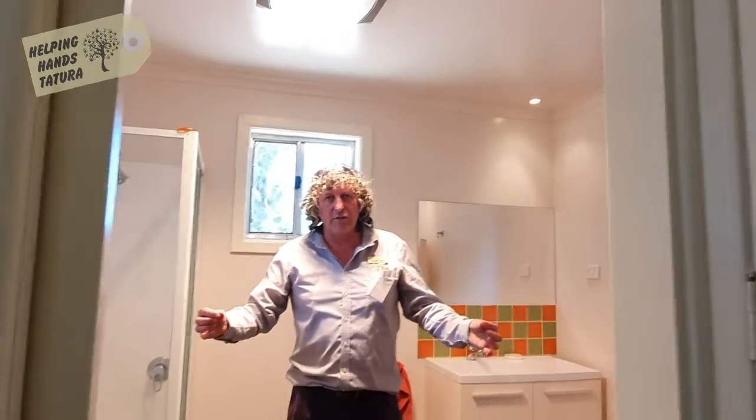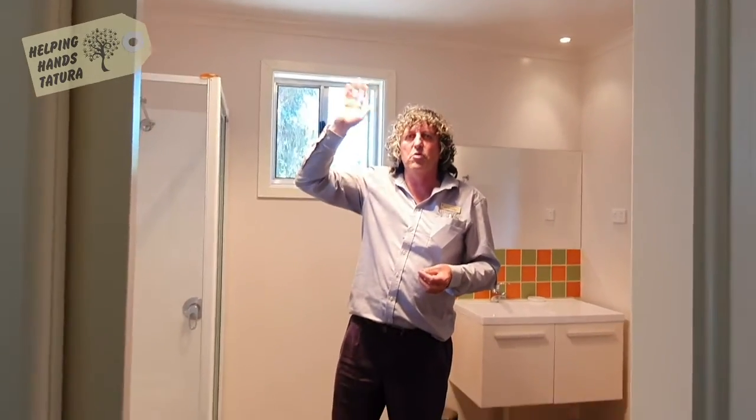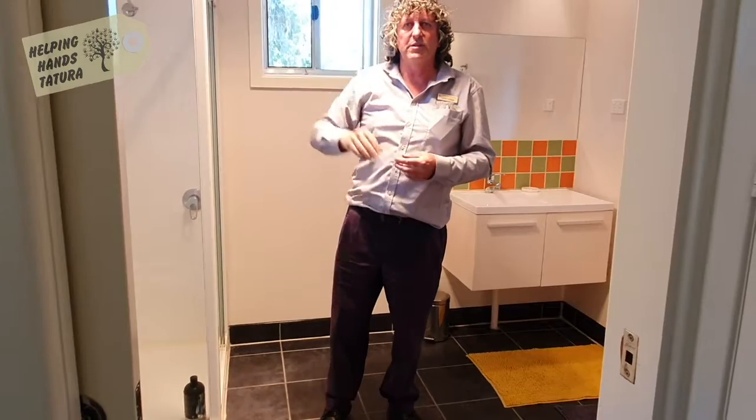So the way you address that is make sure you isolate the bathroom from the rest of the house. We've got a sliding door, which is invariably difficult to seal, but we can reduce the leakage by putting one of those brush seals on the bottom of the door that we talked about earlier. And that reduces the adverse impact of the permanent leakage that comes from these devices.